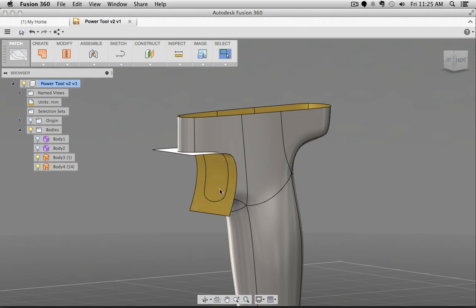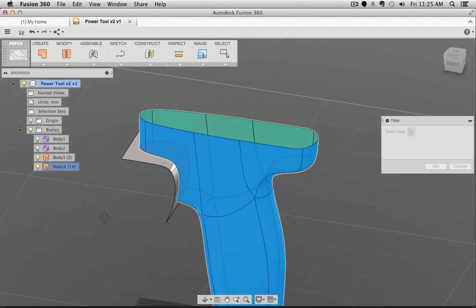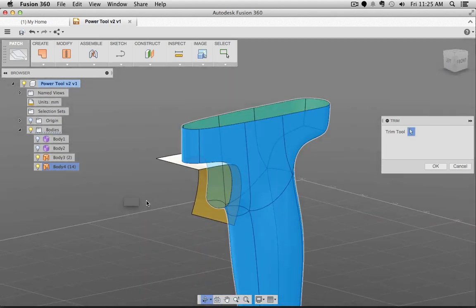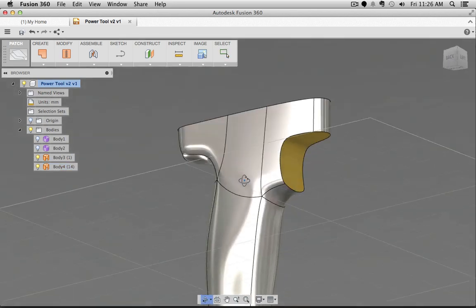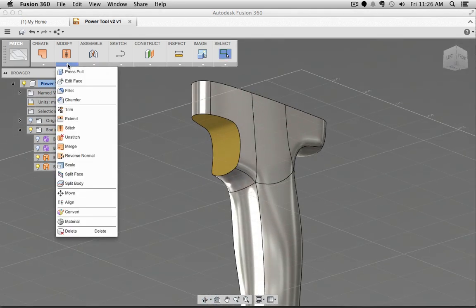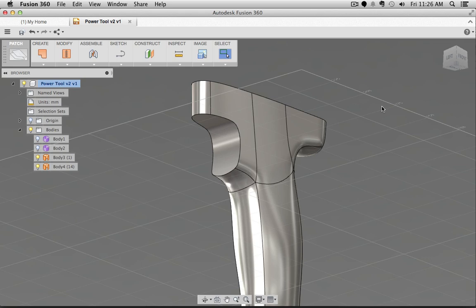Okay, so let's say I would like to close the front part. So for example, I could go with the trim tool again. For example, select my handle. And then I use the handle basically to cut the outside out. So see, I can click it. And again, the software can calculate where are those intersection lines. And based on how those two objects intersect, the software knows how to cut everything away. You see, it's still pretty much like working with foam. And you draw your blueprints, and then you take a knife or a bandsaw and just cut through it. Pretty much the same.